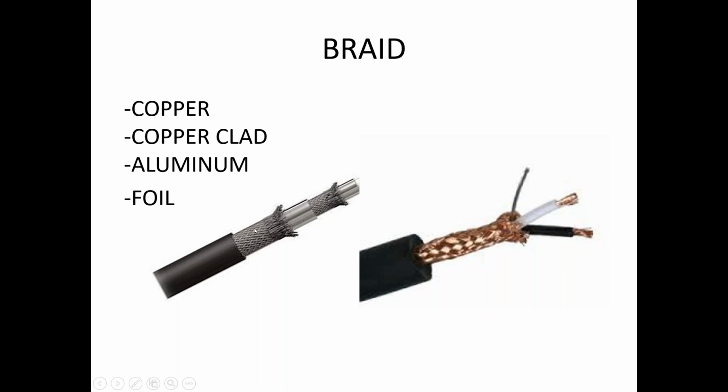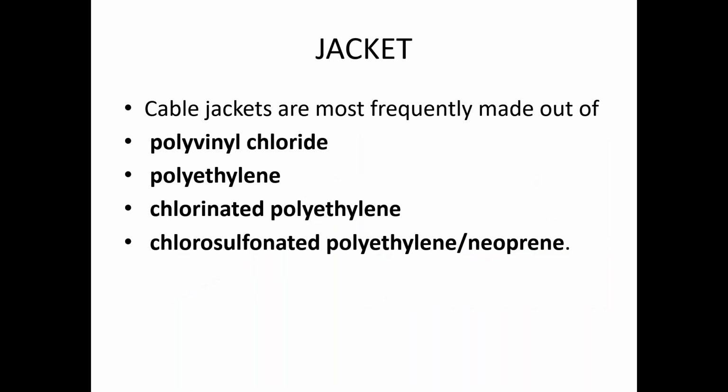So you're going to pay for braid. If you buy a cheaper cable, it's going to perhaps be more loosely braided like this. We talk about braid in percentages. This is 100% coverage. This might actually be 90% coverage. You're paying for that, and it's a reason why you might consider paying a little bit more.